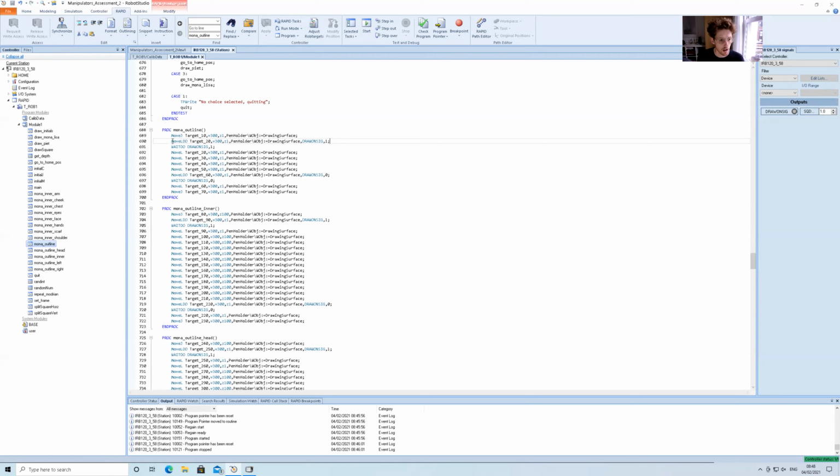So here we've got a MoveLDO, and this basically sets a digital output halfway through the end of the last curve of this movement. So it sets it high, which means we are on the surface of the work object. We're drawing all of this stuff, and then at the end of this movement, we're going to stop drawing. We're going to turn off the TCP trace. We're going to wait for that to happen, because the robot moves at a much slower speed than the way the program runs.